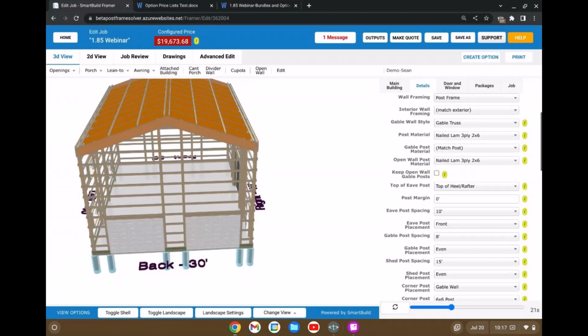Okay, so if it's a 20-foot door and the post layout comes 3 feet off the jamb post, we would go ahead and keep that post at 3 feet off the jamb post. Okay, so you would check that box that we were just talking about. I would check that box as keep layout. Yeah.